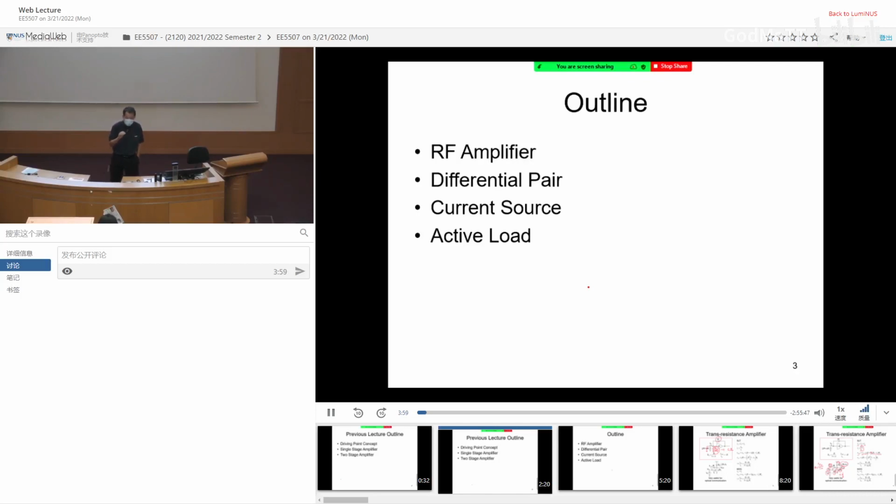And more importantly, I'm going to highlight that a lot of people think that as long as you have two paths, or dual path, that is considered differential. There is actually a so-called differential circuit, which we like, and there is another thing called a difference circuit. A difference circuit is kind of no choice, it's better than none, but it's not going to be as good as differential. So I'm going to highlight that.